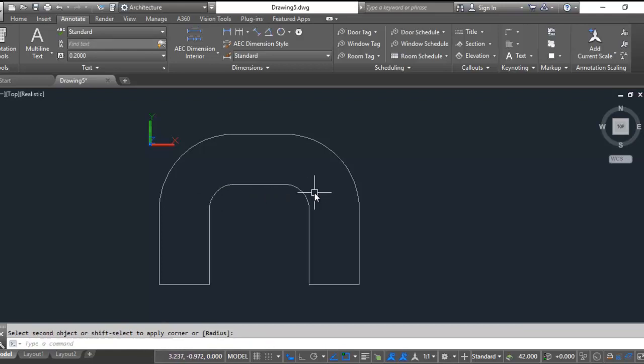And that's looking good so far. Now out here, it's not shown, but it's implied that this would also be that same 0.5 radius, so I can just hit spacebar and continue the command because it remembers that 0.5 radius from before. So there's our overall beginning shape.